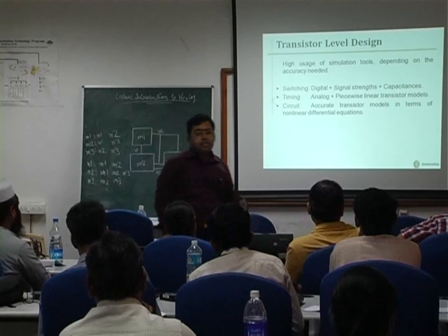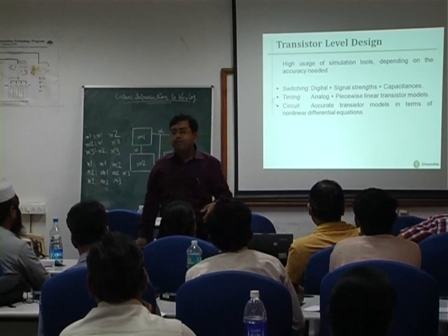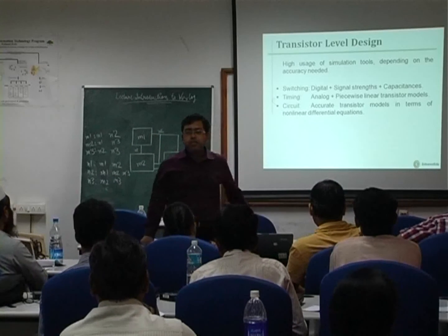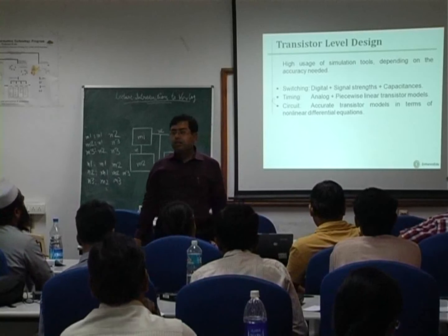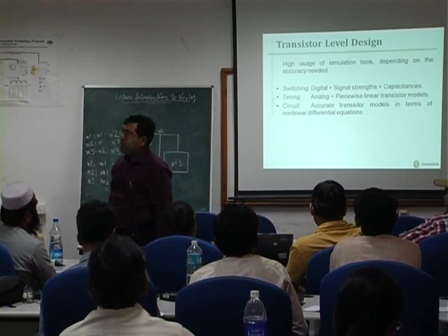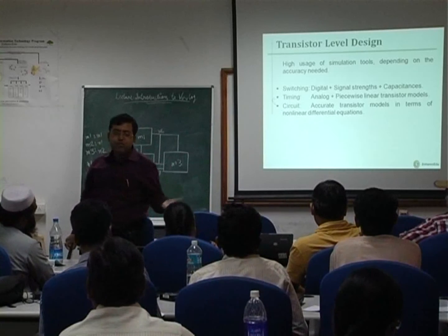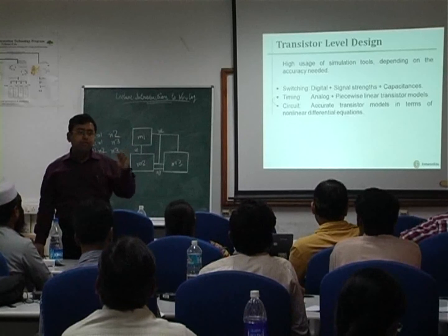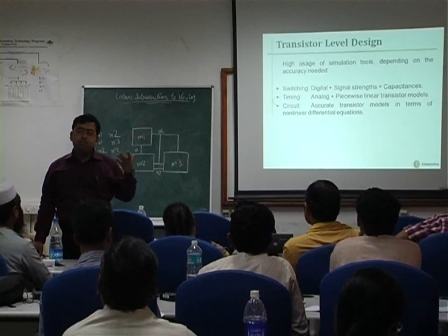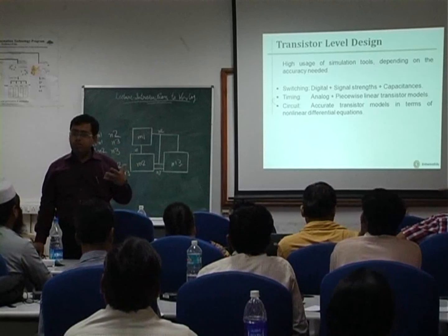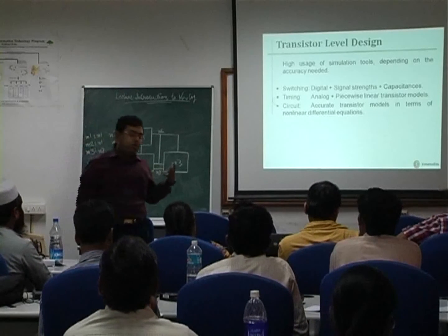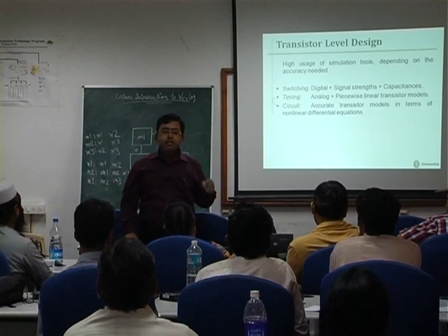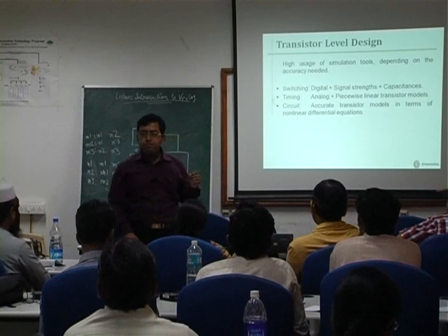And for analyzing these circuits, we have to use the notion of models of various components and devices that we use in the circuit. For example, when you use a MOSFET in a circuit, you have to describe a SPICE model of the MOSFET to express the behavior of the transistor in terms of simpler components.